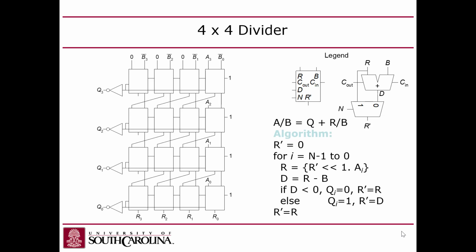Now, if I had subtracted and it worked out for me, for example, if I subtracted 1 from that, the 2's complement of 1 would be all 1s, right? So I would add that, and I'd have a 0 carry, 0 carry, 0 carry, 0 carry. But I'd have a carry at the end, right? So I'd have a carry out, in which case I knew that I had a 0 result or a non-negative result, right?